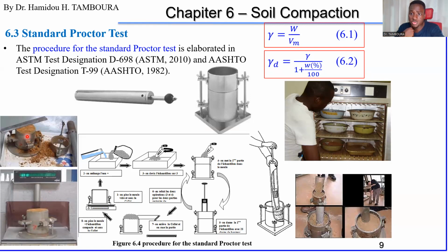It's too much. To do that, you just use this kind of plate. Of course, you cannot use plastic because you are going to dry it. Use this kind of plates. First, you have to know the weight of your plate, because as you can see, they are different shape, different size. You weigh the empty plate, these plates, or if you don't want, you don't even need to weigh the empty plate. Just put the wet soil inside this plate.